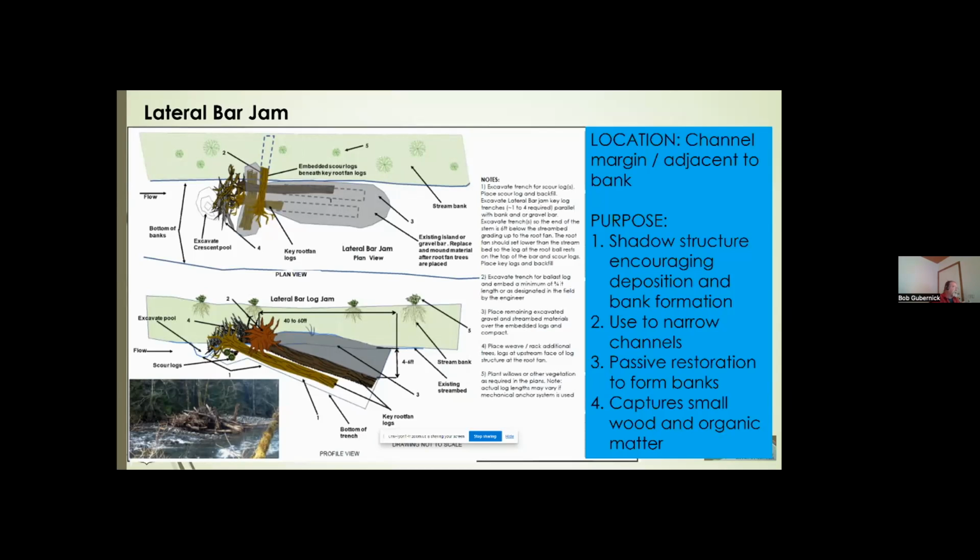Typically when we're building that, the material that we excavate out of there to place the wood in and bury it is mounded up behind there. But as the structure works, again, there's a low, no velocity zone behind them, and materials in suspension and materials being kicked up during larger storms, bankfull events, and greater mound up material on the backside of these. And again, slowly but surely, passively through time, narrow the channel back up again to a proper width.